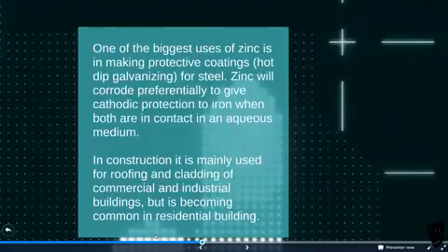Preferentially, it will corrode. Sacrificial. It's a sacrificial metal or cathode. Anode. You can call it an anode if you want to as well. So it protects the iron, protects the steel, especially when they're in a very wet environment.